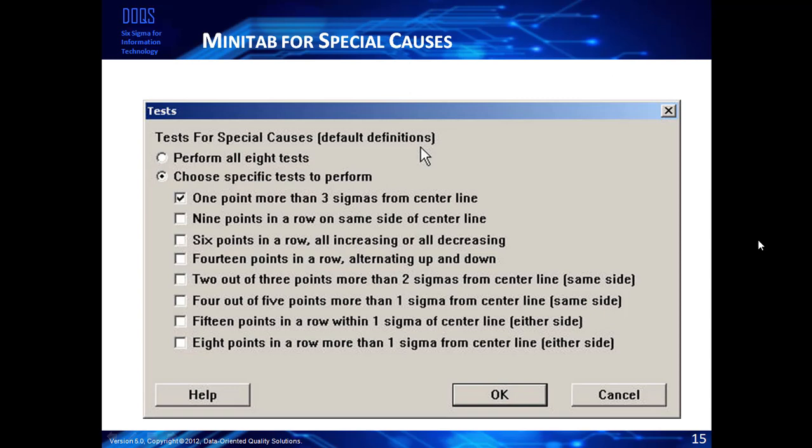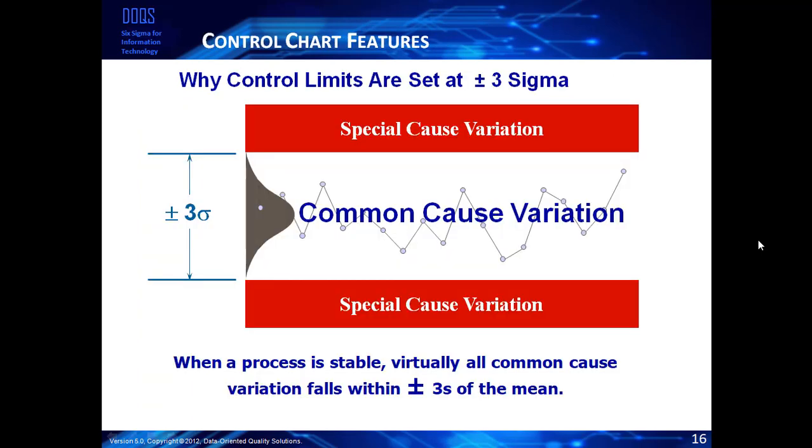There's a set of rules that come out. You can see them in most statistical tools for the ways you tend to look at it. We're basically expecting the control chart to be a normal distribution lying on its side. So we expect to see points back and forth among the 3 sigma distribution, with most of the points toward the center, but definitely some points easing toward the side, the same way you would expect to see under the normal curve. We know those as the Western Electric rules.